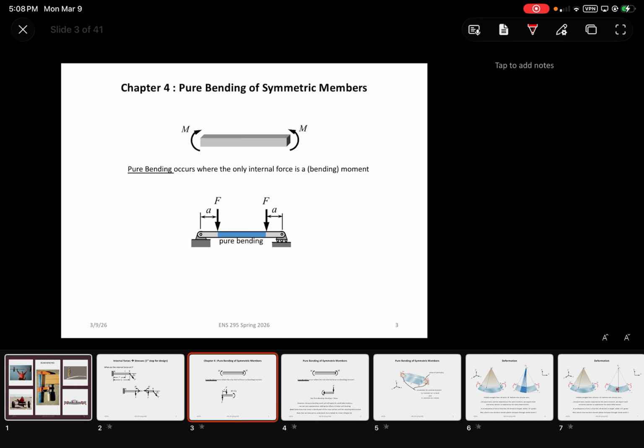You'll learn later on what pure bending looks like from an internal force diagram perspective, but it's basically when the moment is constant in a particular region. There's no variation, and no shear forces causing any variation in the moment. So that moment, when you do force equilibrium, just ends up equaling force times the location where that force is applied with respect to the supports.